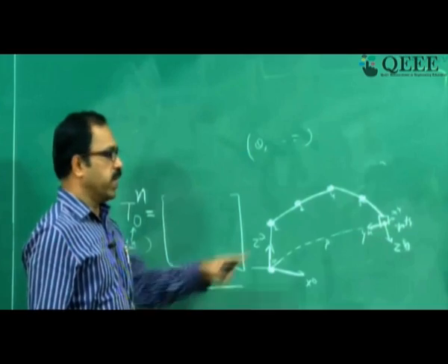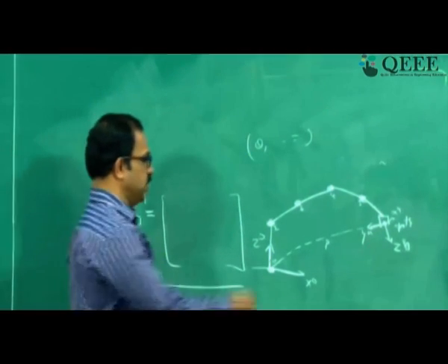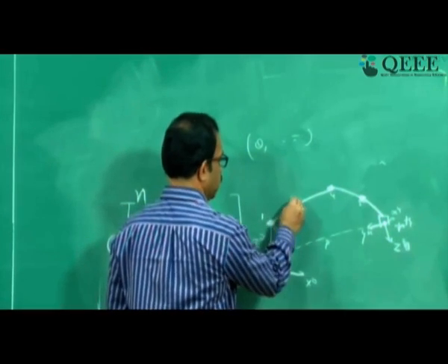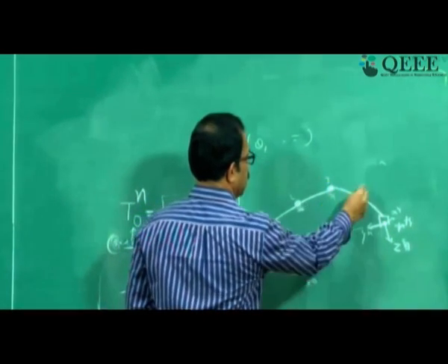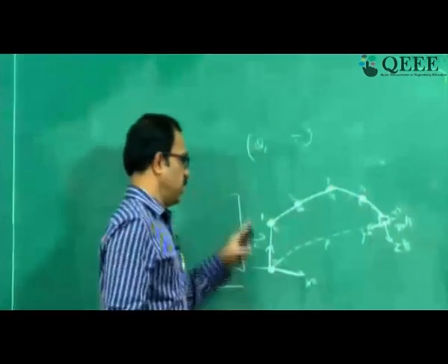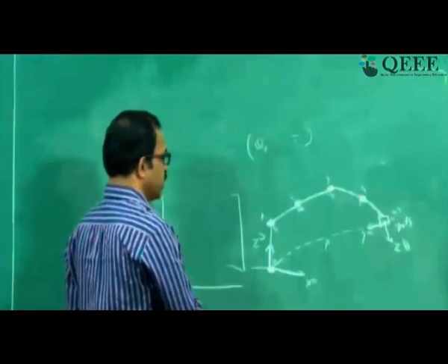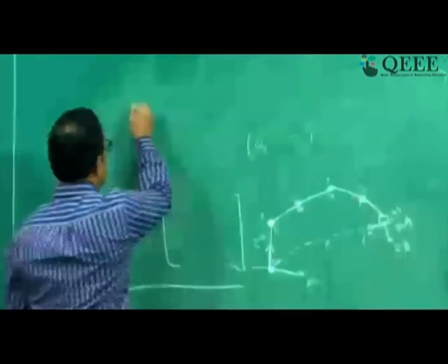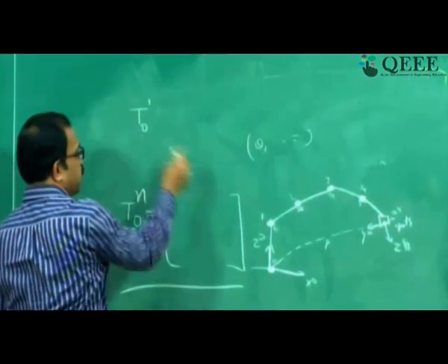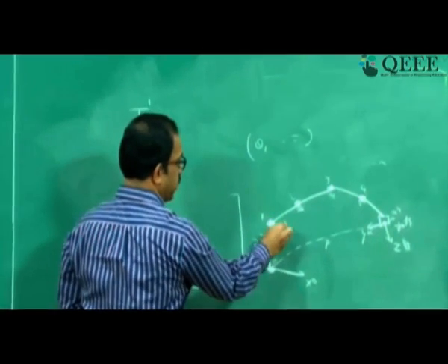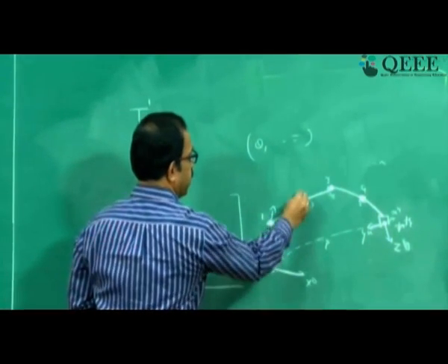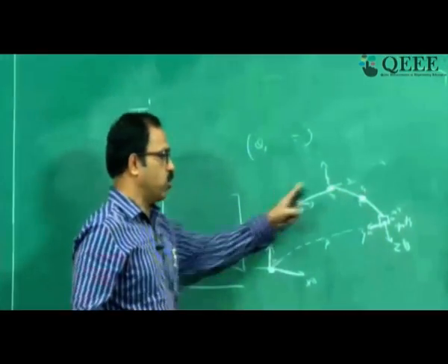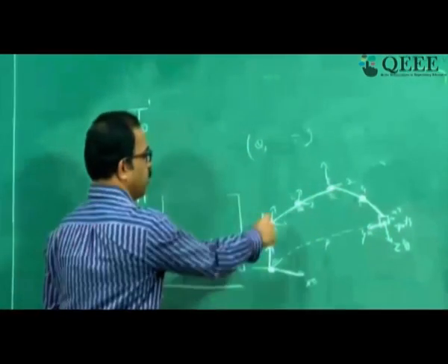Since we cannot get a direct relationship, what we normally do is this. This is the first one, and I number the coordinate frames 1, 2, 3 etc., that is L0, L1, L2, L3 etc. I will take T1 to 0. I will first find out the transformation from this frame to this frame. There is another frame here and another frame here, with coordinate frames assigned to each one. So I look at all the coordinate frames and try to map this one to here.